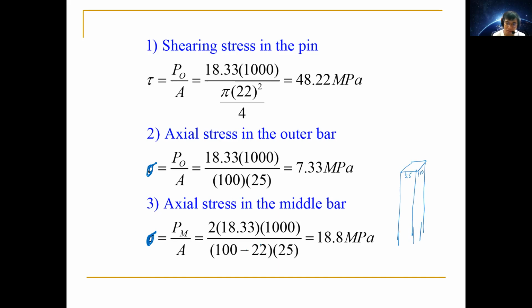So why do you need to take 22 mm away? The shortening of 22 mm is in this axis, not the 100 axis. So that is wrong. It should be 14.66. Again, the shortage of the bar is not coming from the 100 millimeter axis, but from the length axis we subtracted earlier. So this one is minus 22.